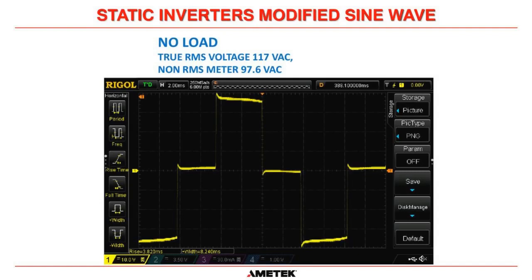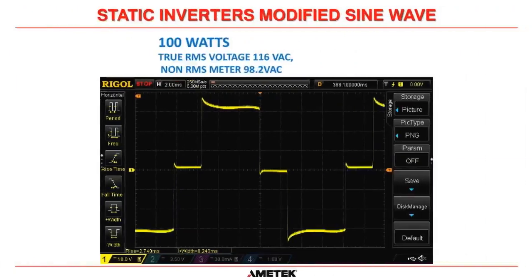Now, Fluke used to make, I don't know if they still do, their 70 series meters, which were great little meters, but they were not true RMS meters. Our industry today pretty much uses Fluke 87s or something maybe a little more advanced than even those. And of course, they are true RMS meters. So we're going to see the effect of this inverter here.